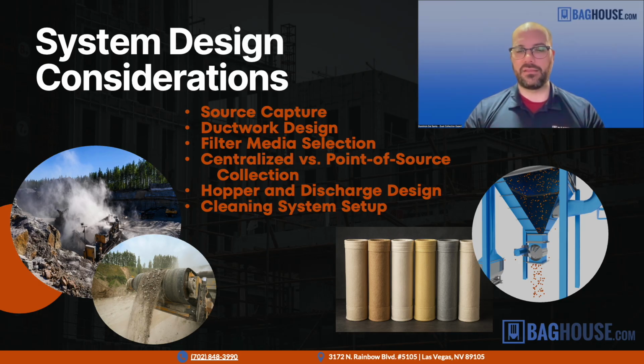Many times people think of those as different things, but a lot of the problems in cement and mining applications with dust collectors can be traced back to the discharge underneath. It goes into a screw that goes over here. That backing up or not being sufficient to remove dust quickly is a cause of a lot of the problems we see. So you have to think of all of it together.